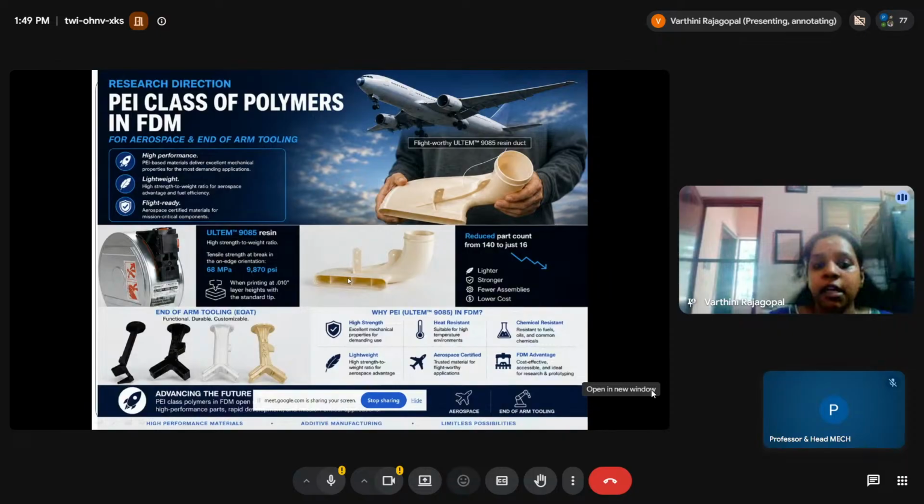So what they have done is they have imported that geometry into ANSYS generative design. They have specified where the loads are going to act. Then they have simulated it. The end result is you have these many possibilities. Each possibility will work for that particular application. Do you think this can be built using a traditional manufacturing process? No. The additive manufacturing process has given a path for constructing these. These kinds of brackets will have reduced volume, reduced material, reduced waste. You can use this instead of the solid one which was shown in the beginning. Let me show.